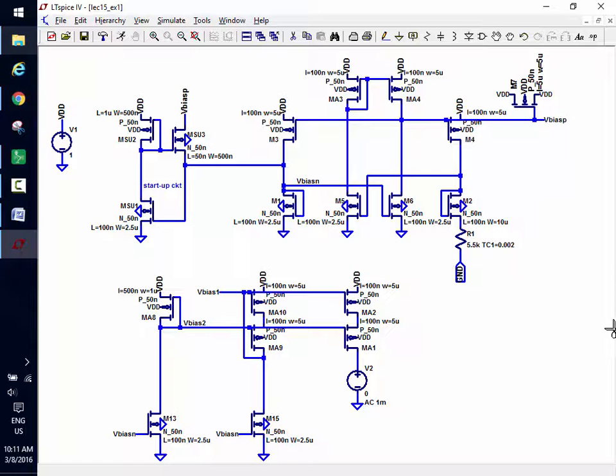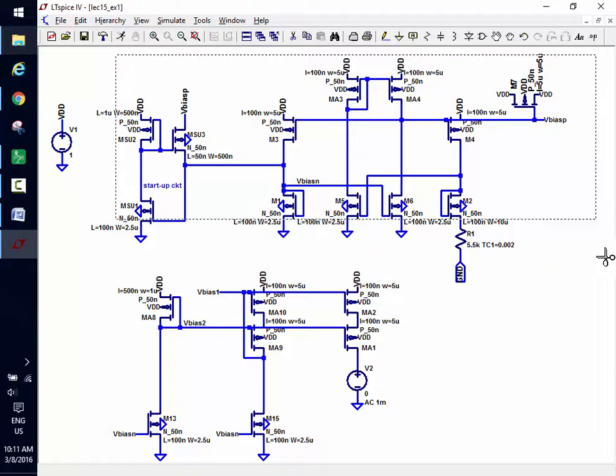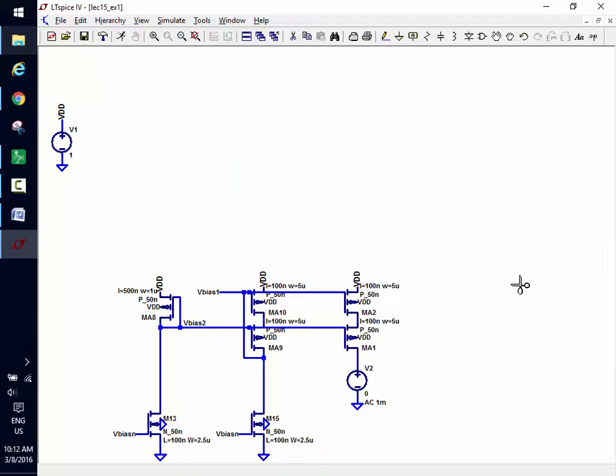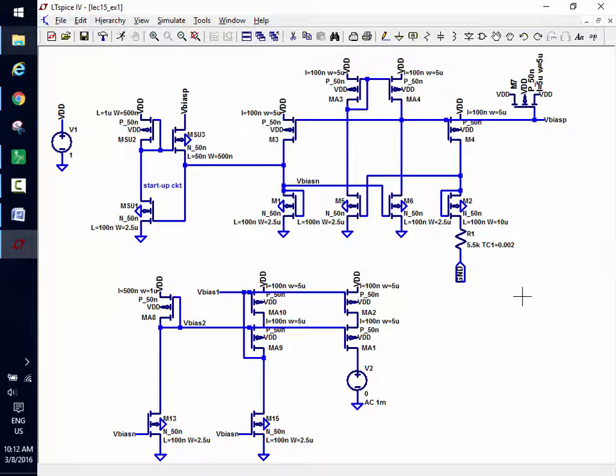All right, why don't I make it easier because you guys don't like the BMR, so the homework problem didn't say you had to use the BMR, so let's get rid of that. Did it say use the BMR? It was already in there. All right, so you want me to use it? You have to, don't you? Okay, yeah, sure, I don't care. Well, if you don't use it, isn't it gonna change? No, I'll just make a gate drain connected NMOS with a 10 microamp current source over here, and I'll generate the V bias. Get the same thing. Because in the simulation, I can use an ideal current source. Are we ready to go?